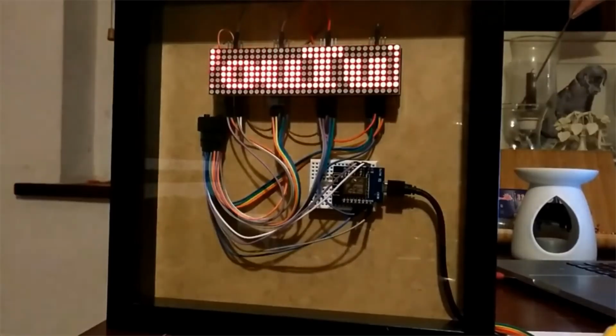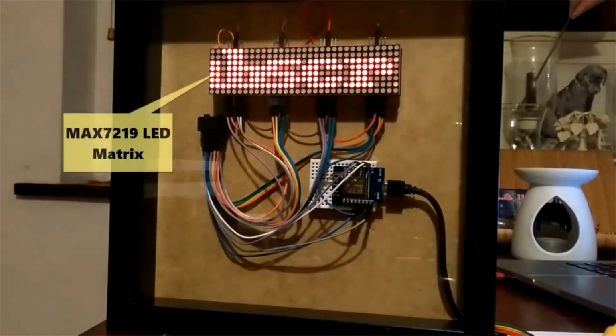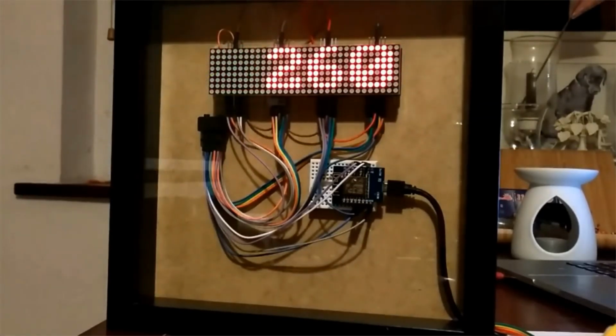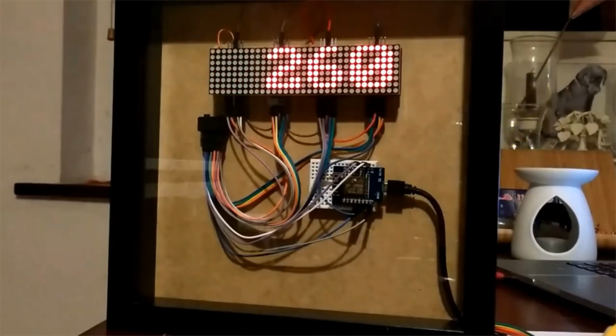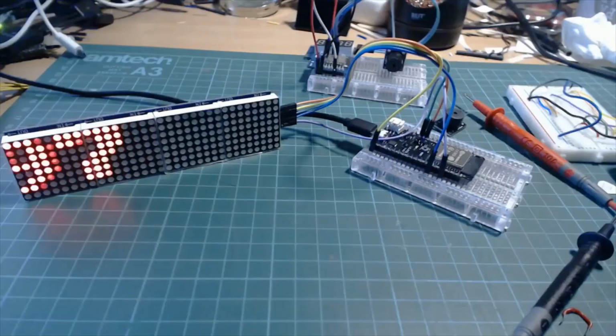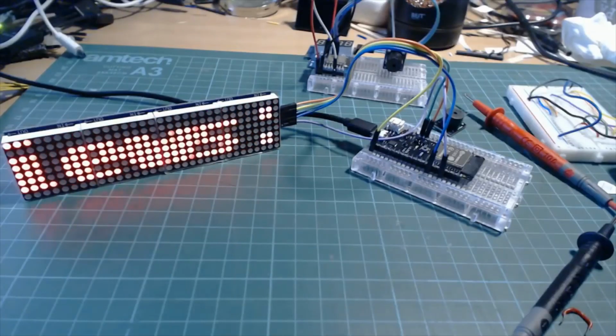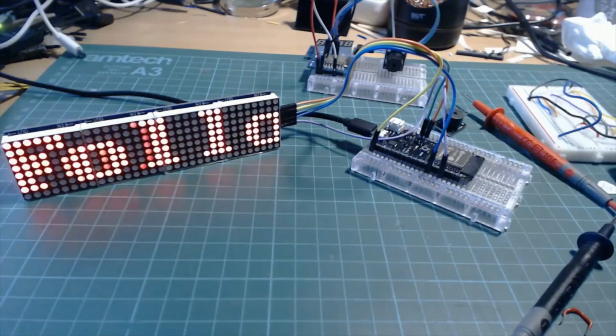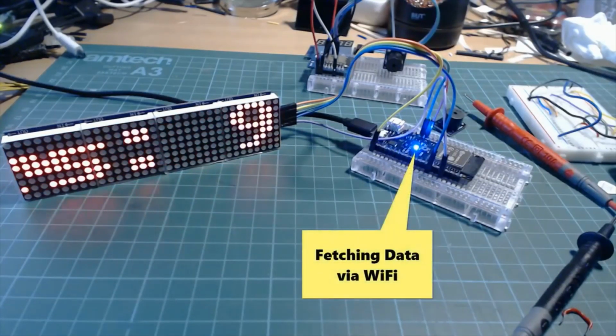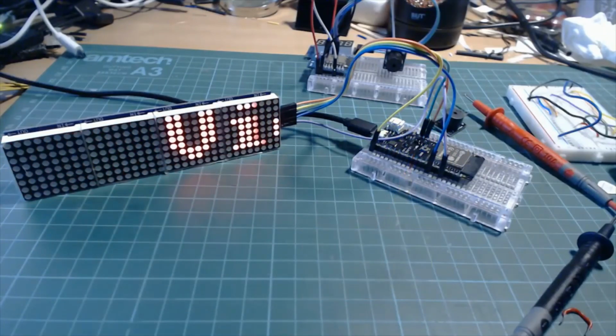To give a more practical example of how this is useful, with one of these LED matrix displays, every time the text moves is a task on the Arduino. So for this social media stats counter I built using an ESP8266, I got around this issue by stopping the text on the screen when there was a value displayed. This gave me a chance to make a background call to fetch new data. But by making use of both cores of the ESP32, using one to drive the display and the other to make the network calls, we can continuously scroll the text even when we're fetching that data from the internet.